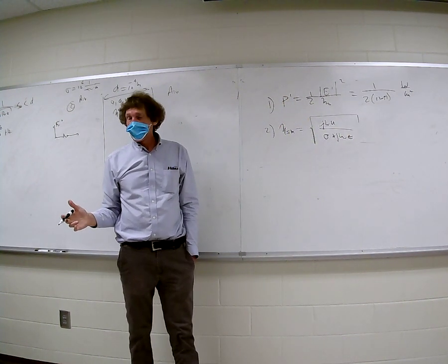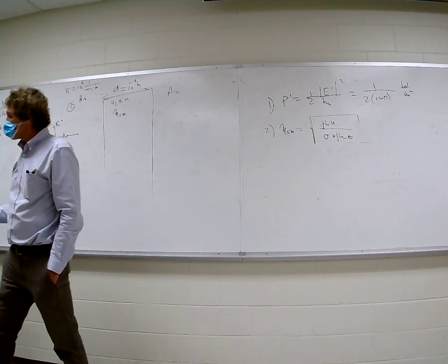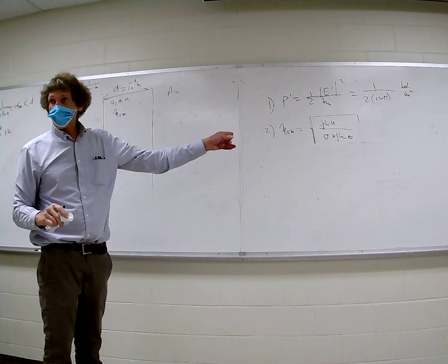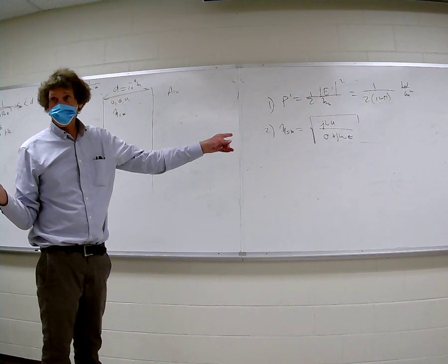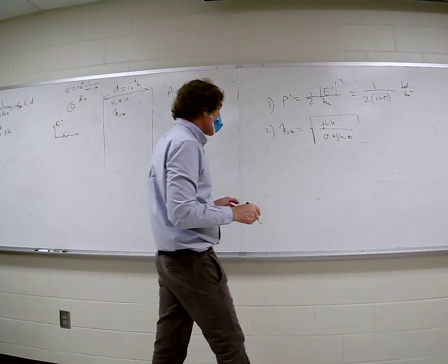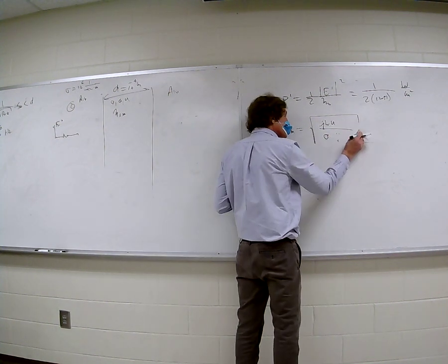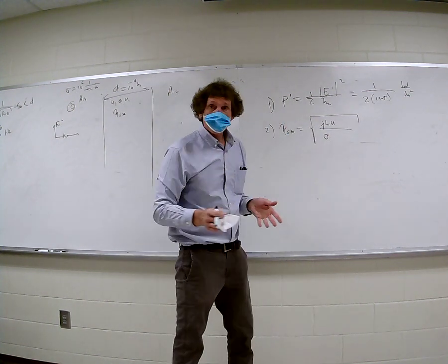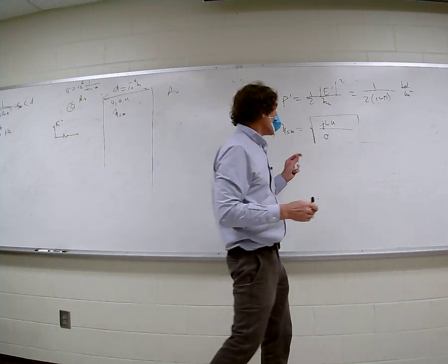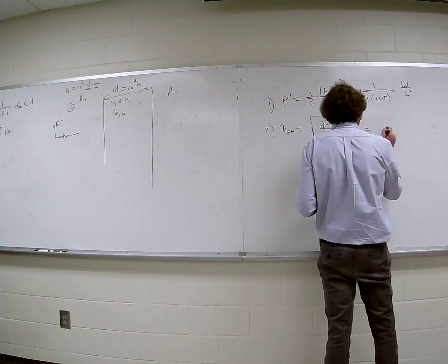Everybody? Now there's one caveat here. This is a very good conductor. You could go ahead and put in j omega epsilon, but it's going to make no difference. Do you follow me on what I'm saying? Everybody? So you don't have to have this because it's so small. You could include it and it will not change anything. You can try if you don't believe it. So if you did that, it's fine. You don't need to.